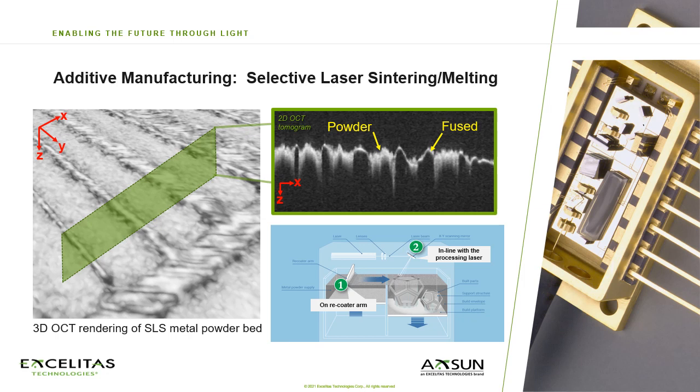Selective laser sintering is an additive manufacturing technology which uses a high-power laser to fuse particles of a metal powder, layer by layer, in order to create a 3-dimensional object. As an expensive process, reducing scrap due to defects incurred during printing is critical. Even if parts cannot be recovered while printing, it's important to scrap parts before more time and materials are expended.